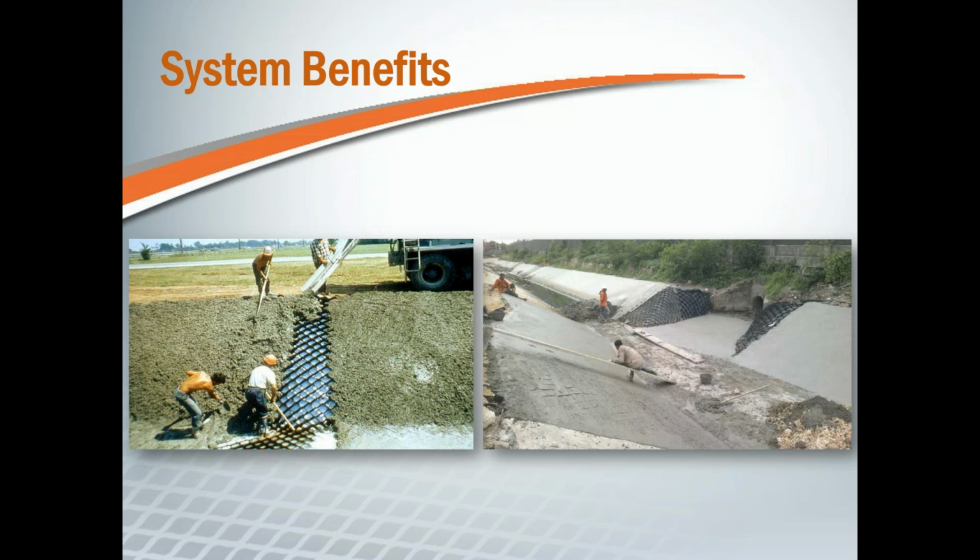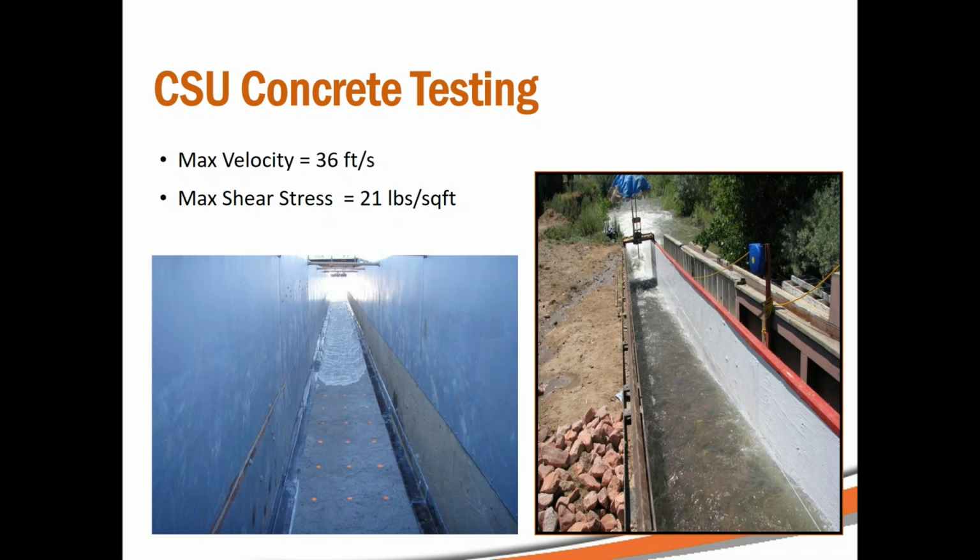The unique aspect of the concrete being poured into the individual cells means an easier to pour, higher slump concrete can be used. The slump can be adjusted in the field as necessary to handle different slope angles, even near vertical angles around culvert outlets. In general, 3 inches of concrete-filled GEOWEB protection replaces 5 to 6 inches of reinforced concrete. And compared to articulated concrete blocks, ACBs, the GEOWEB system is both cheaper and safer to install. Costs are 2 to 4 times lower than ACBs, and no heavy equipment is required to lift the GEOWEB panels, so it's safer for workers.